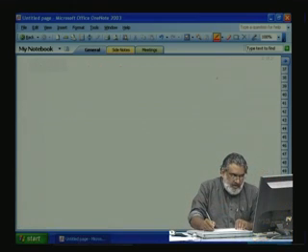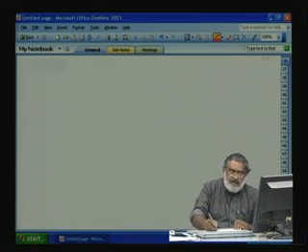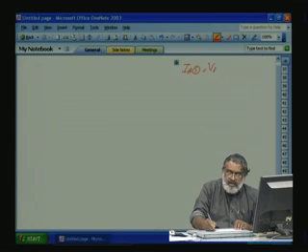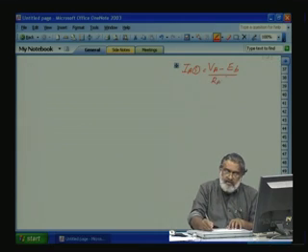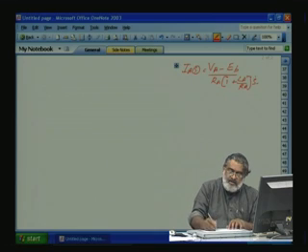So before coming to the block, let us again, for our reference, write down our equations. IA(s) is equal to VA minus EB divided by RA into 1 plus LA by RA into S, that is one equation.